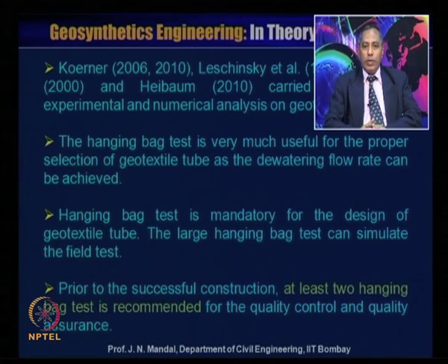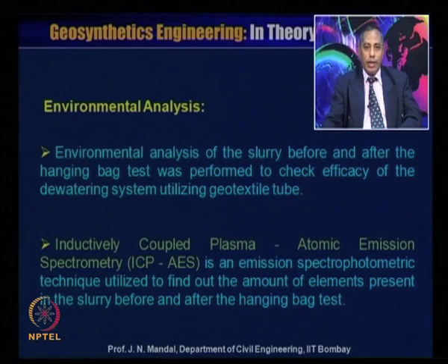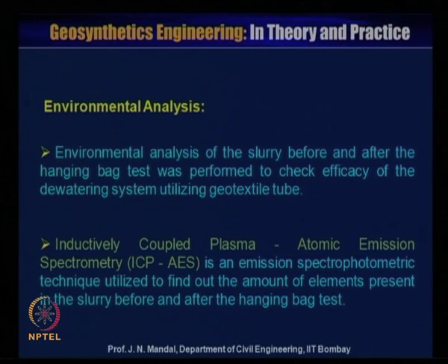So, the hanging bag test is mandatory for the design of the geotextile tube. The large hanging bag test can simulate the field test. Prior to successful construction, at least 2 or 3 hanging bag tests are recommended for quality control and quality assurance. Now, from this test we have also performed some environmental analysis.